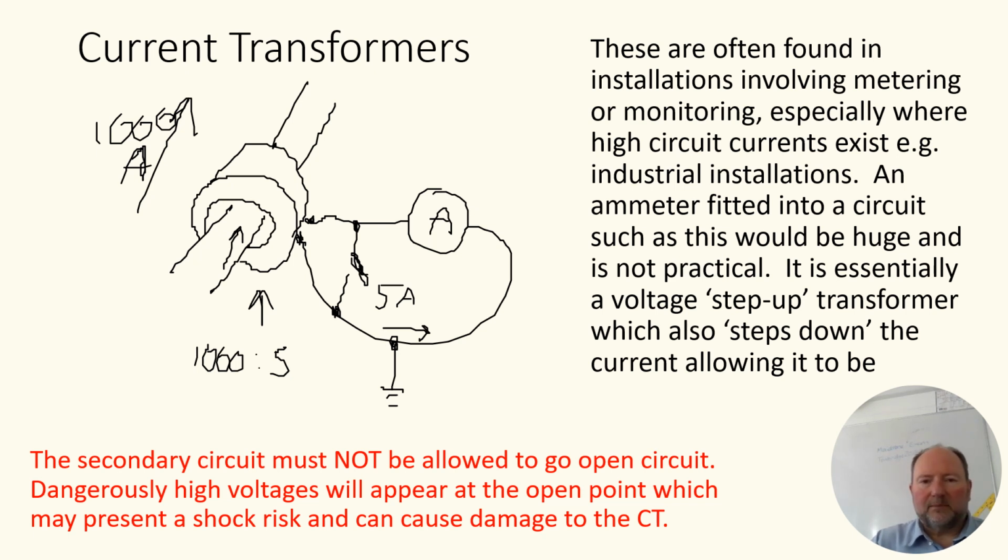You may recall an ammeter is a low resistance device, and the upshot is that if you were to take the ammeter out of circuit in order to do maintenance, you're going to get really high voltages appear at this point. That could be rather sad in terms of it being a shock risk, and the voltage could eventually damage the insulation of the windings inside the current transformer itself.